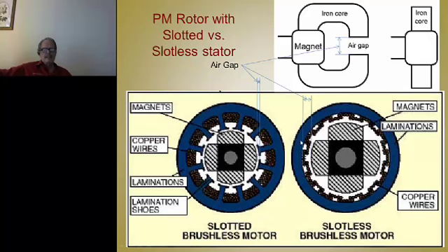So where are the forces on this wire? I guess they're there, and mathematically they're still correct. But what these conductors do is they magnetize this tooth here, and let's call this a north pole. Let's call that a south pole, and that's the way it would be magnetized if I have one side of a coil in there going from there to here.